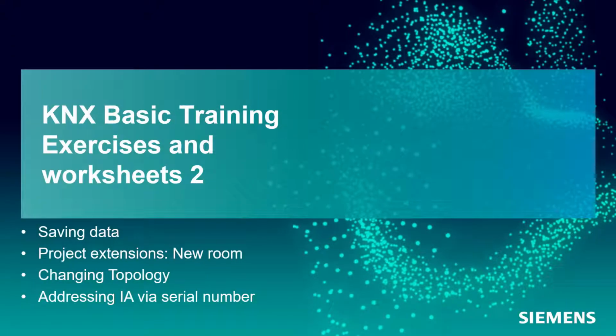Welcome to the second part of our KNX Basic course practice. We continue our practical training with the topics saving data, extending the project by another room, introducing group and central function control, and we will also change the topology by using the app Siemens Address by Serial ID once more.